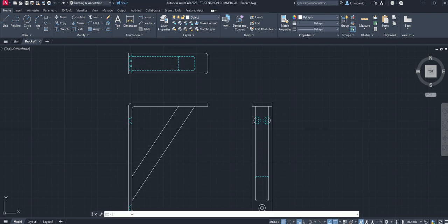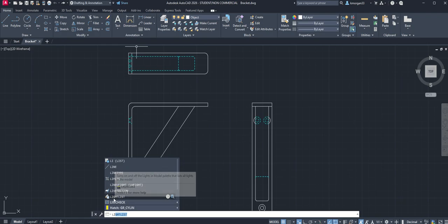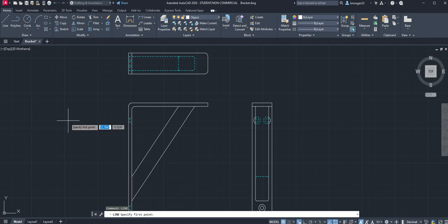Of course, typing all the time just strains your hands. So if you want to call a line, you don't have to type everything anymore. You can just type "li", and it is going to show you a list of commands starting with li. You have line type, limits, limit weights. Look at this, everything that starts with li is going to pop out, and you choose where you want to go, and then do your input.